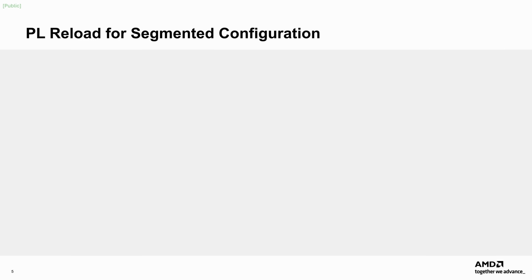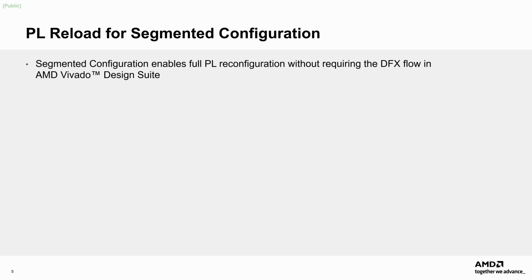First, let's look at an overview of how PL reload for segmented configuration works. The segmented configuration approach enables users to delay delivery of the PLPDI image. Moreover, users can dynamically reload the configuration of the PL on the fly, changing the functionality of the design in the PL domain. This effectively provides a simplified entry point to a dynamic function exchange DFX-like solution without requiring the use of a full DFX design flow within the Vivado design suite.